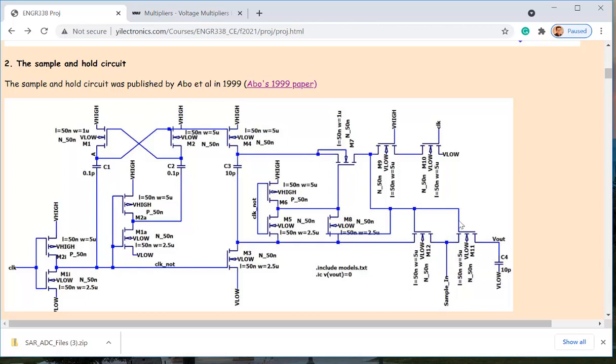If you just keep this at VDD, is that correct? It's VG minus VS, right? So when VS changes, if you just turn it on using VDD, then your VGS changes. Yes, this voltage will be passed to here through this pass gate, but it's not ideal because of the change of the VGS. And why it's not ideal? We're still studying that, right?